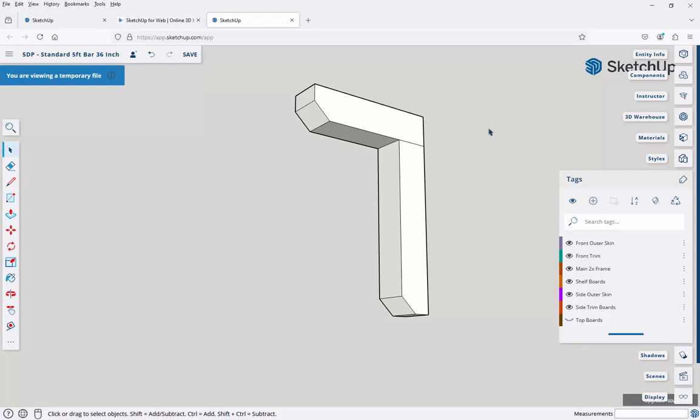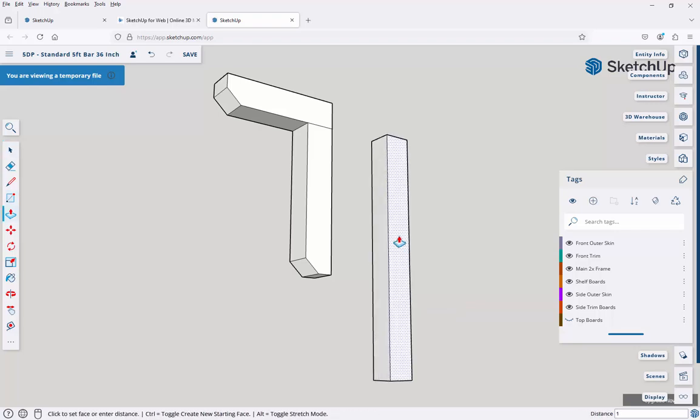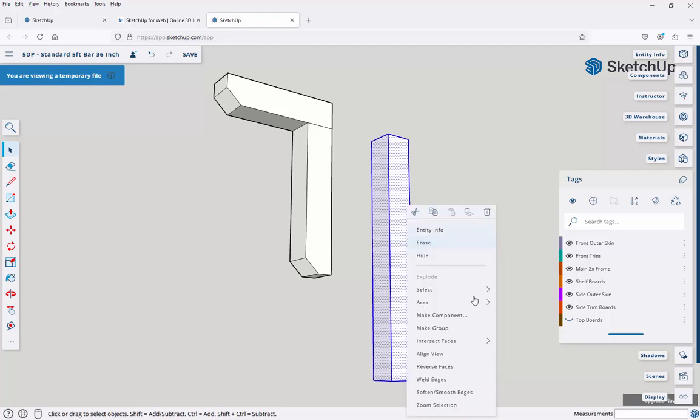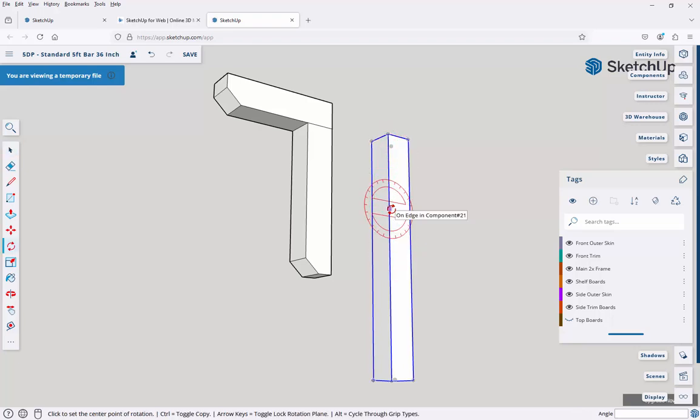So we're going to come in here. We're going to go back to our rectangle tool again. Again, we have to define what plane, and we're going to do 1.5 comma 10, comma 14. 1.5, and then we can triple click on it, make it a component, and then we can rotate it.